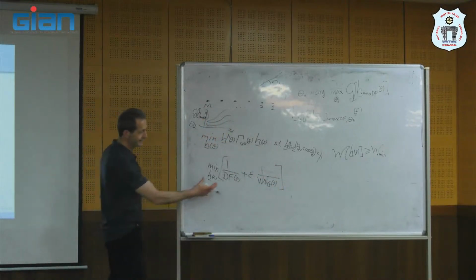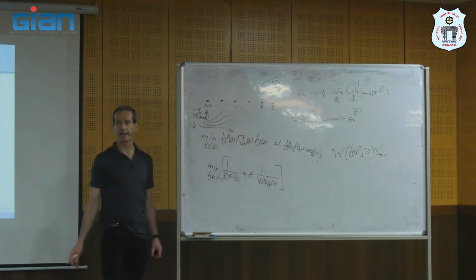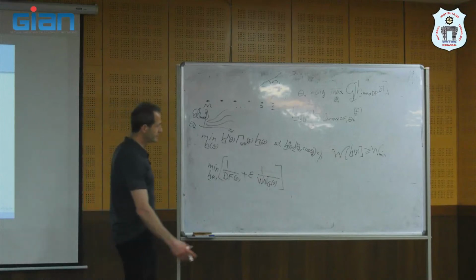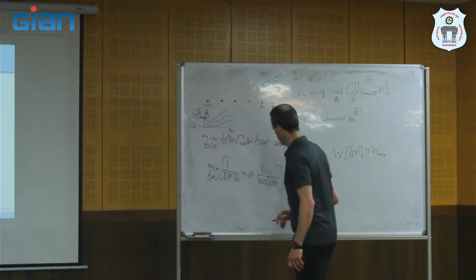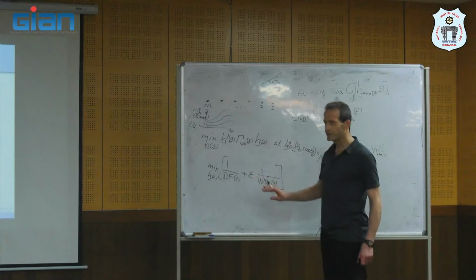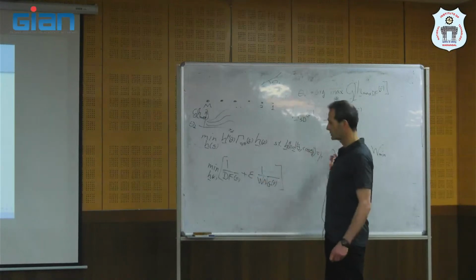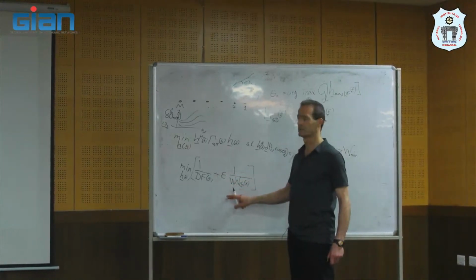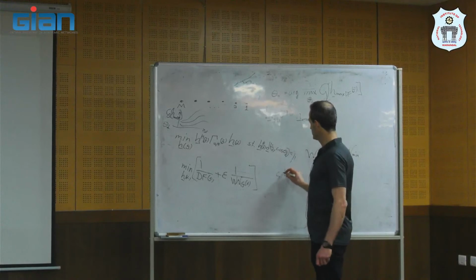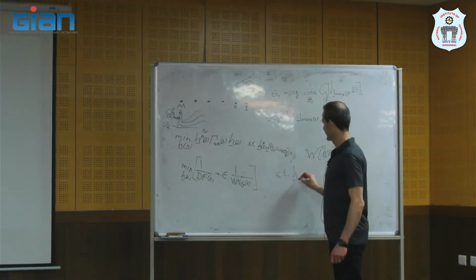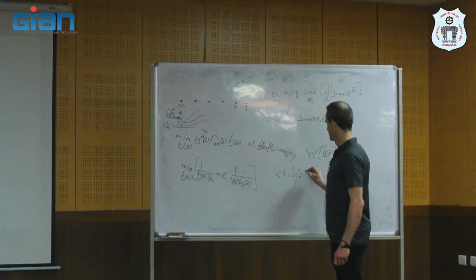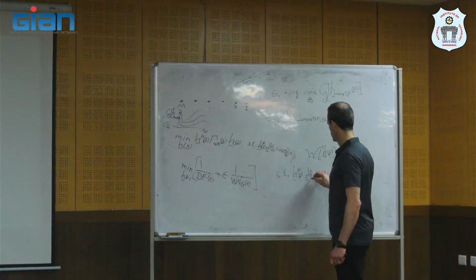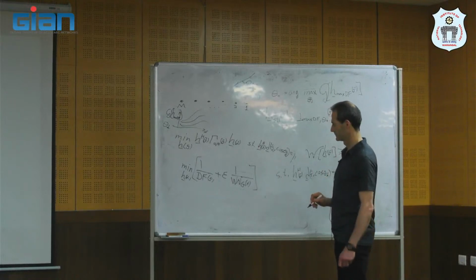And then I can write these expressions, the array gain for diffuse noise and the array gain for white noise, more specifically. So when I have an additional constraint, I can give it a certain weight, subject to H^H d(f, cosine theta d) equals 1.